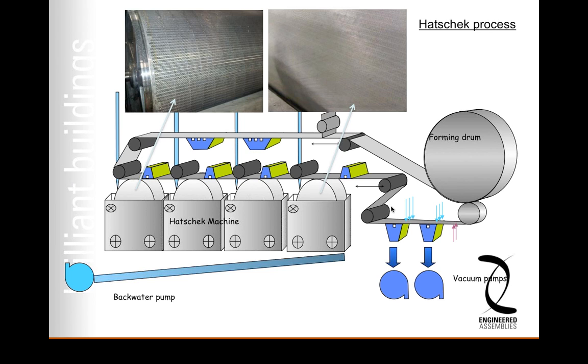That slurry of cement, sand, water, and fiber goes into these vats, and different amounts of it are applied to a piece of it, and as it spins around this conveyor belt, it gets thicker and thicker. When it's at the right thickness, it's cut and then put under pressure and cured. Why that matters is it's just such a simple manufacturing process. They can make it in very large quantities. This isn't a batch process where they lay out panels and layers and have human interaction that can vary from one panel to the next. It's a very automated process.